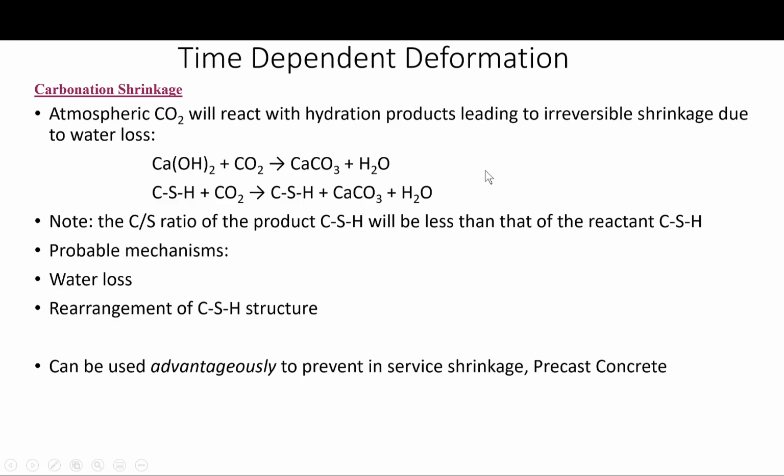So the carbonation of the calcium silicate hydrate is known to change the bonding characteristics of the material, which could account for the irreversible nature of the accompanying shrinkage. So carbonation can be viewed as promoting changes in the calcium silicate hydrate that normally only occur at much lower relative humidity. Okay.